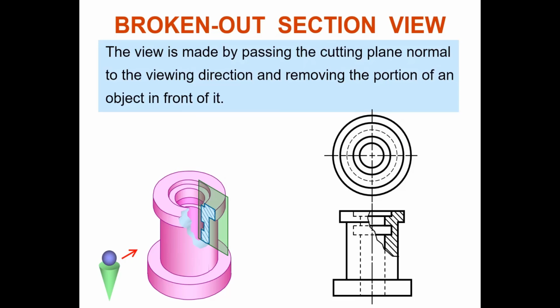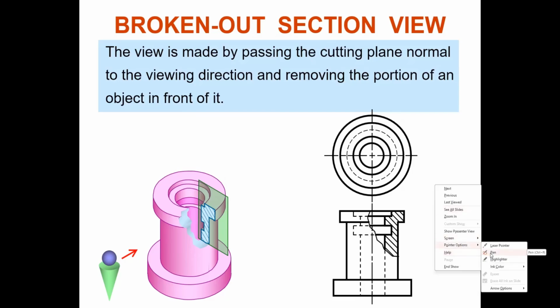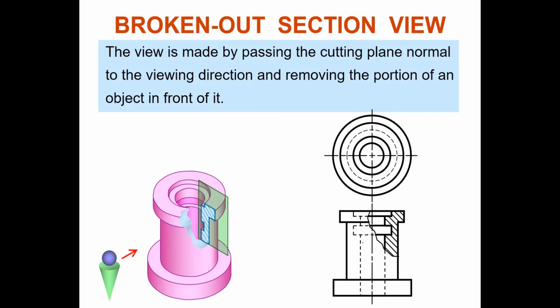Clear or not? Clear. This one, if it has hatching in a little bit, one region or portion of it, it means that broken out section. Okay. What about the rest? Should hidden line be there or not? All of this, can you hidden line in? No. Hidden line should be shown or not? Yes or no? Your answer is No. Not showing. No, wrong. Sorry, this one is required. We take note, class. This will sometimes be asked in tests, guys.